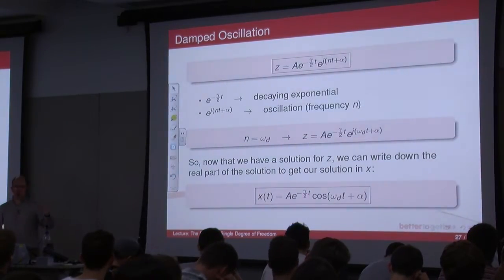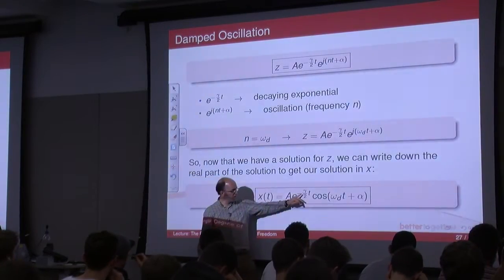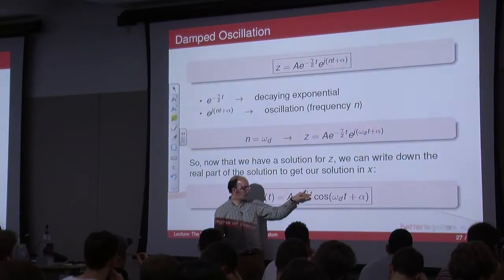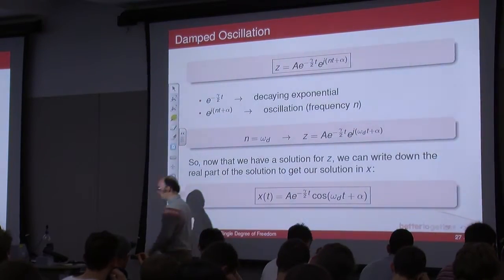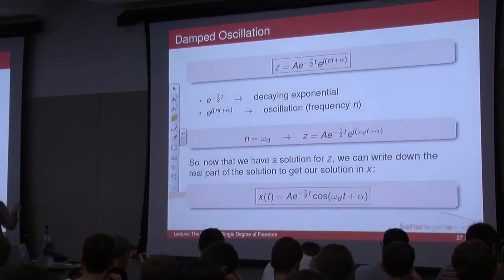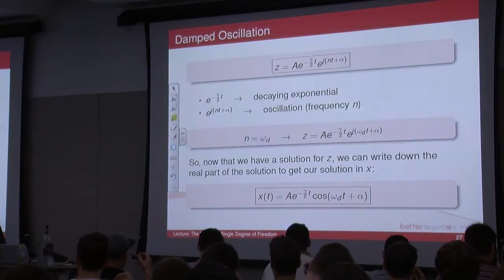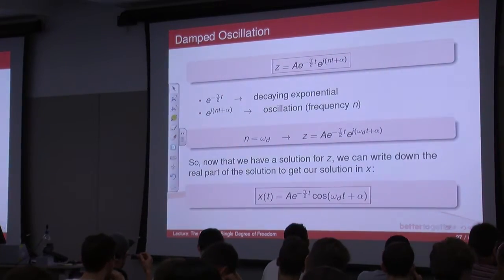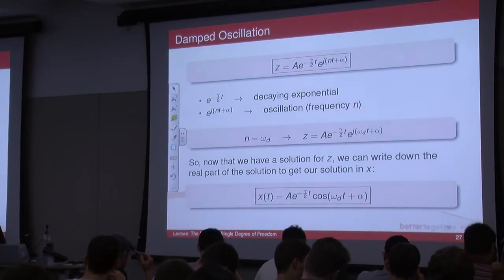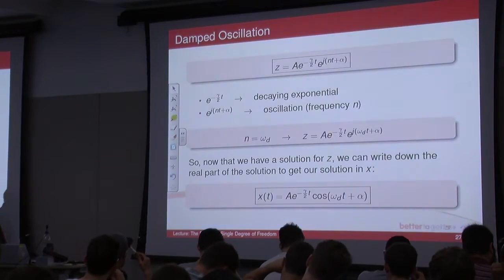Now we'll cover this when we come to the alternative terms section, alternative terms for gamma. You'll see that change, but let's not worry too much about that right now. You can see quite clearly the equation is made up of an amplitude, which is what you set it off as, and an oscillation of frequency omega d. Let's not worry too much about what's going on here, that depends upon initial conditions, and the fact that this term will start off and then decay away.